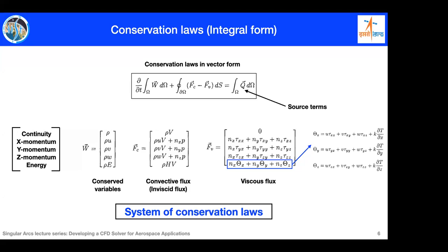When we form it into the compact form, it becomes much easier to see how we would like to discretize and which terms we would like to compute. This is basically partitioning the equations into different modules, which we will be able to discretize and solve separately. I will go one by one. First we will go through how to calculate the convective flux, then how to compute the viscous flux, and so on. Then we will go to the time update, or the partial derivative in time.